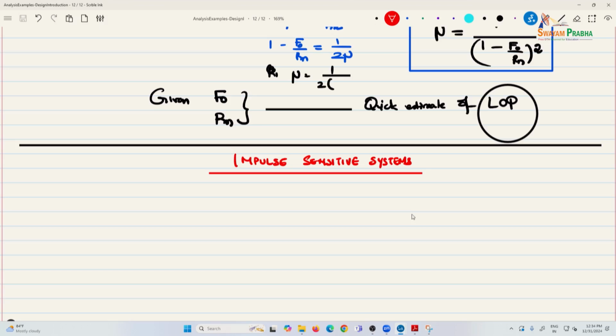Keep in mind, we talk about a response modification factor. Be careful when you talk to people in the seismic design world or you are working there. It also represents ductility, but there it represents the ductility you are designing it for. There it is only one thing, you have a capacity, elastic capacity.